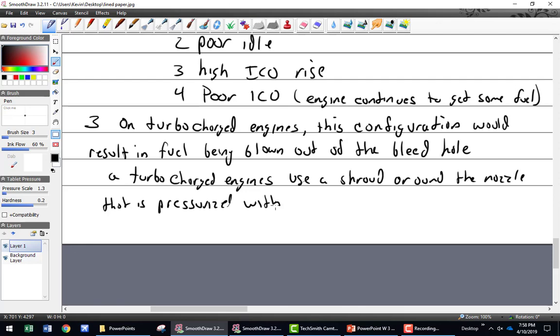Upper deck. Why can't they use manifold? What's the difference between upper deck and manifold? Upper deck is straight out of whatever compression system you're using, the turbocharger outlet up to the plenum and the throttle valve. Throttle valve to cylinder is manifold. So why am I specifying upper deck pressure, making a big deal of it, instead of saying, well, as long as it's higher pressure air than ambient, why not just use manifold?